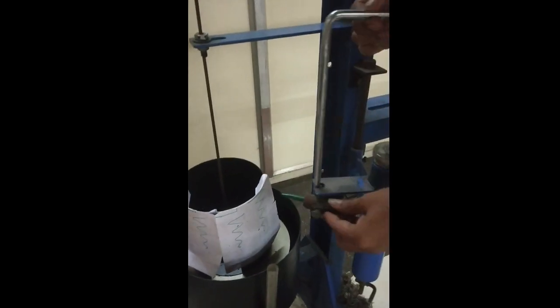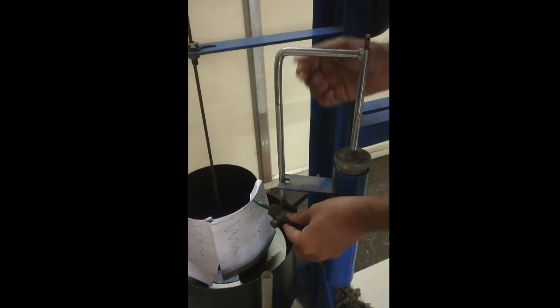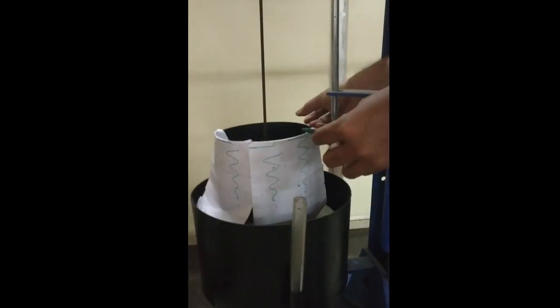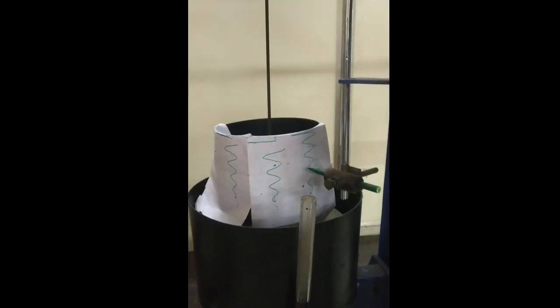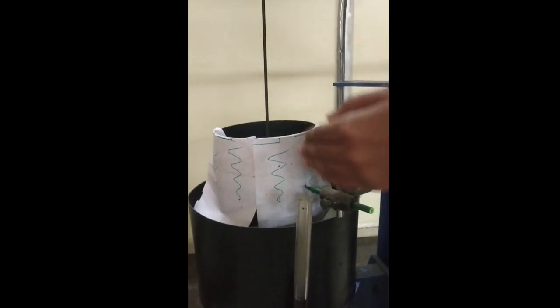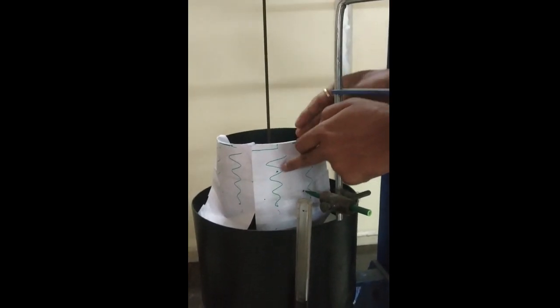Now, if you observe, I am putting this stylus initially at its top position. When I provide the torsional vibration, with this viscous damper the pen moves in a downward direction with constant velocity, which plots a graph of this kind. With the help of this graph we are finding out the amplitude with damping and without damping.